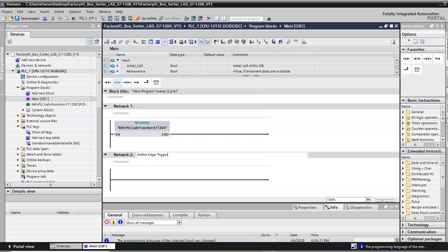And these are all of the signals that we're going to use based on a rising edge or a falling edge. And if you look in bit logic, what we have in here are these gates that look like your normally open type gate, but it has either a P or an N in there. The P means it's a positive edge, or a leading edge. You know, it's going from the no voltage state to a high voltage state, and N is just the opposite. And you can just drag and drop them onto the square, and that'll drop this in here.